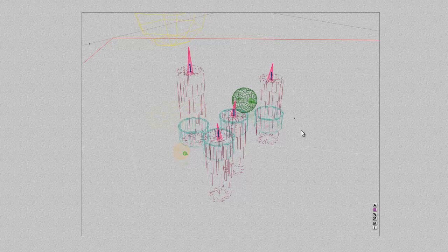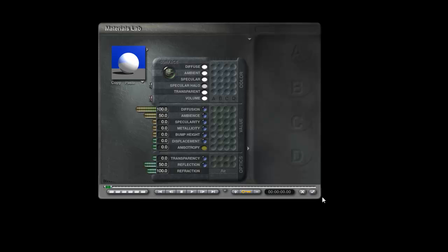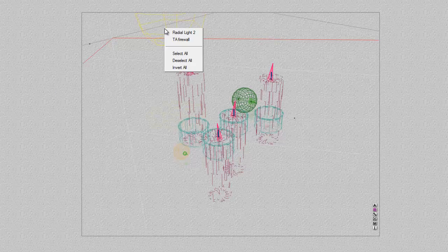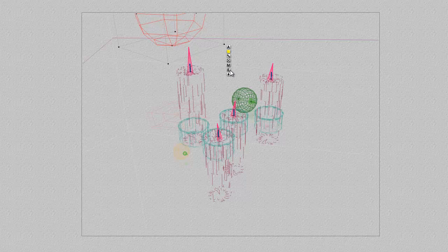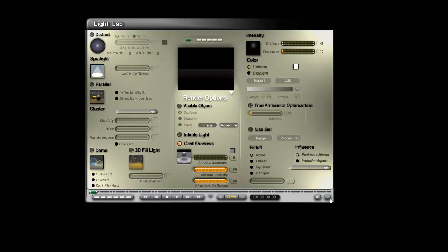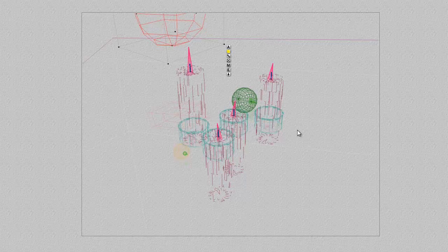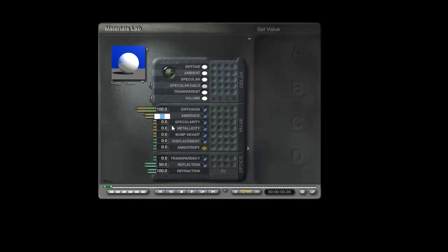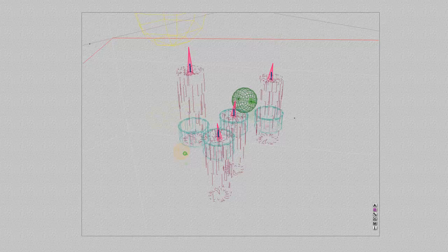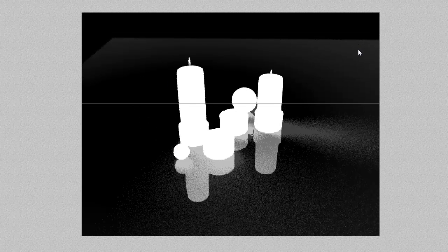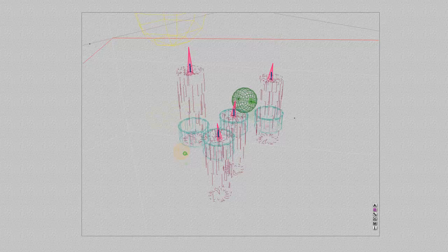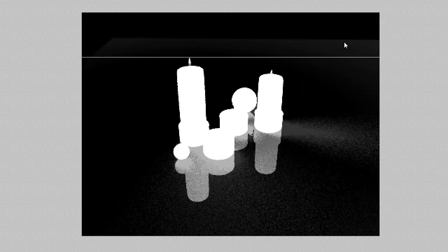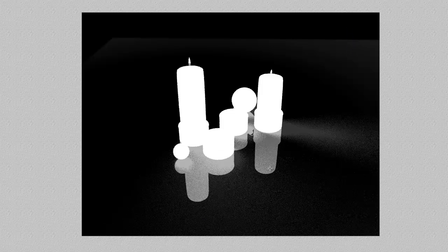So I need that to be a bit brighter, so I'll take the ambience up to 50 and then have to cut more out by using the light. So use the light, and I could make it none, and that will allow it to cover more area. That's a bit better now. Still a bit too glow, so I'll take it to -2. Oh, that's better. Right, and then if I take the ambience down here, let's try 25. So it's just a matter of juggling these figures. I can see it's still slightly glowing there, so I'll reduce it to 20. So now I can still see a little bit maybe of glow there, but not much. I suppose that's close enough.